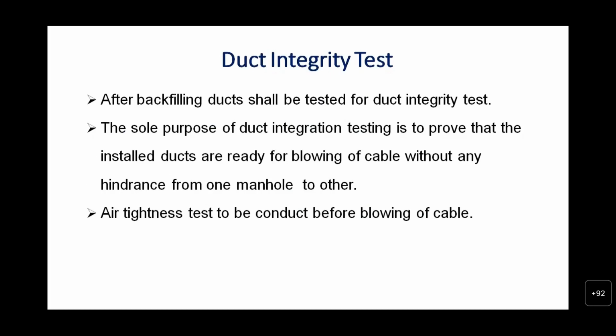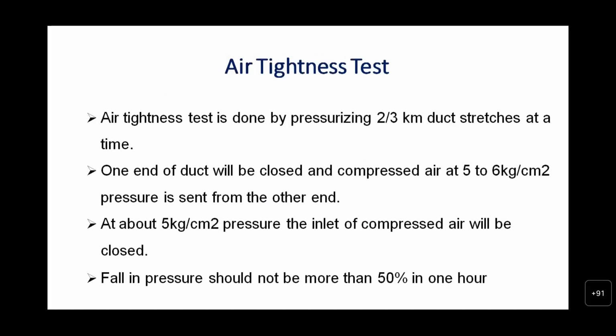The sole purpose of the duct integrity test is to prove that the installed ducts are ready for blowing of cable without any hindrance from manhole to manhole. The tightness test is to be conducted before blowing of the cable.